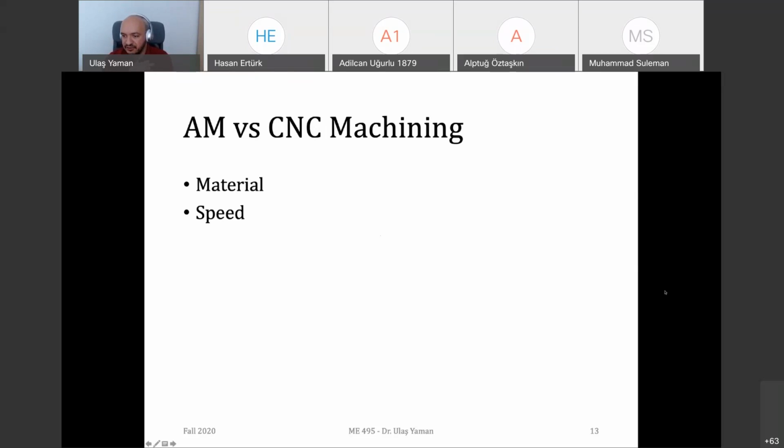Yes, there are other issues. Your friend said that as the part gets more complicated, additive manufacturing will be much better. Yes, since if the complexity of your part is getting higher, then that means you need to spend more time on fixture design, more time on mounting your part, arranging maybe some global axes, some different axes, or arranging the sub steps. It will take lots of time.